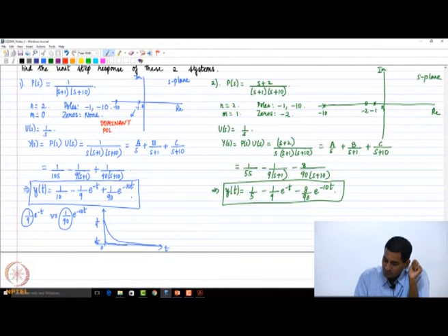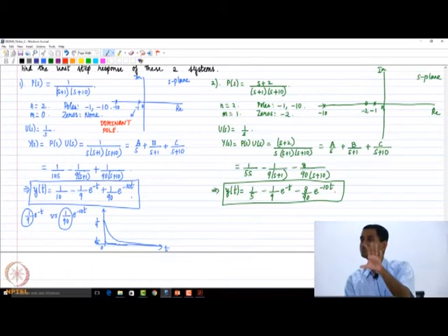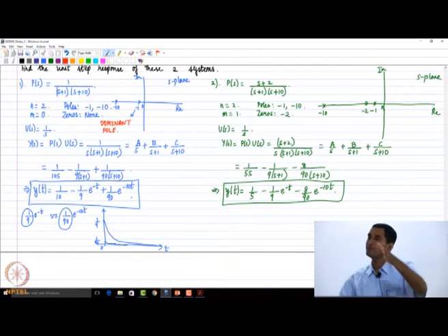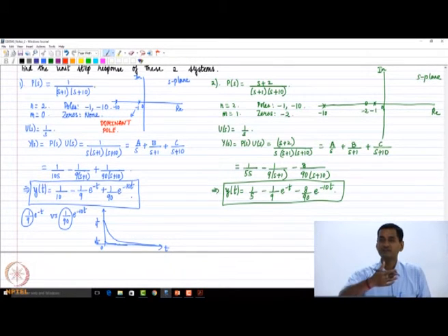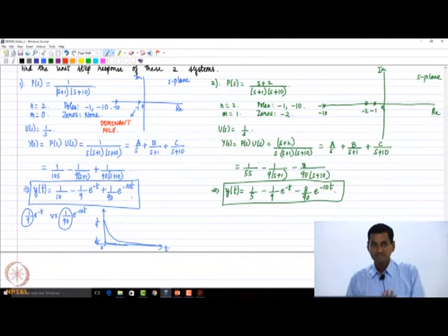Okay, so dominant poles are those poles that are closer to the imaginary axis. And why are they called dominant? Because you can observe that those poles are going to come as the exponents of the exponential function, and they are going to have a more lingering effect on y of t than those which are farther away into the left half of the s-plane. Okay, so that's why they are called dominant poles. Okay, so please remember this discussion. Is it clear what we discussed?